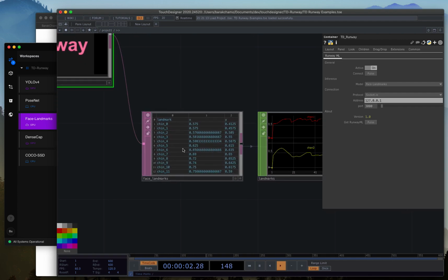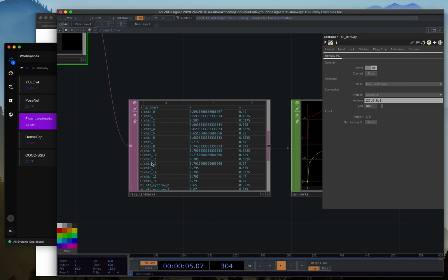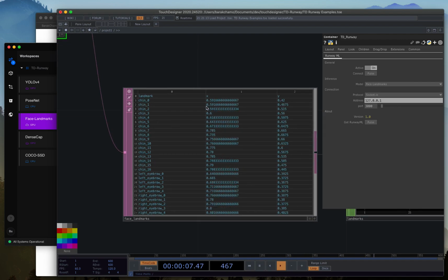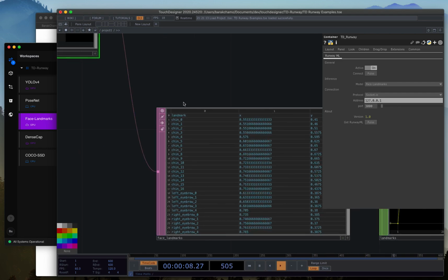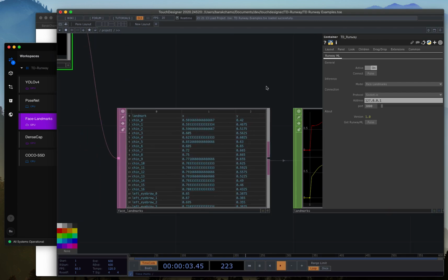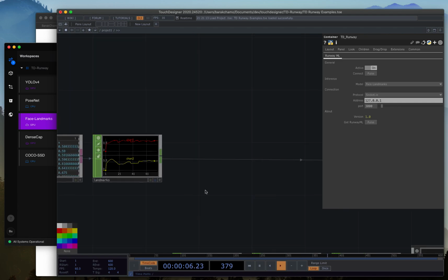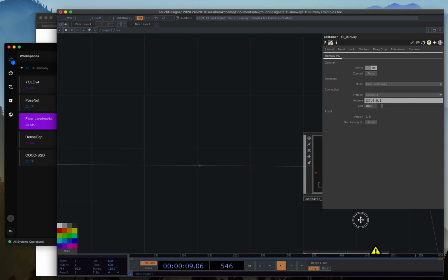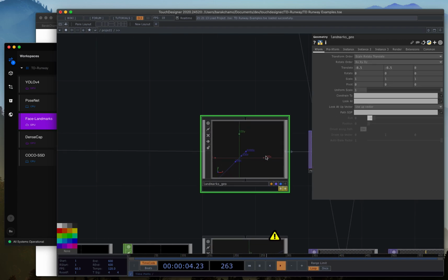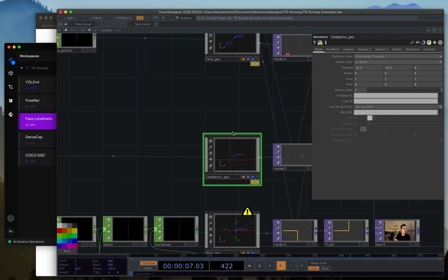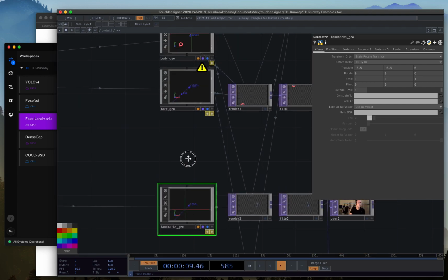So face landmarks will give you all of the labels for the landmarks on the face and only a single person. So you get the labels here because it's easier to match. I tried to keep the Python code inside TouchDesigner to run as fast as I can, just because the process is already pretty slow. So we have X and Y, and it's a very similar process to instancing this as it is with PoseNet. So it converts everything to a CHOP, uses that on an instancing of a geometry. If you're curious how it matches the images exactly, it's because it's using an orthogonal camera.